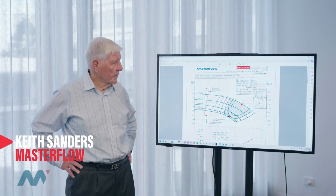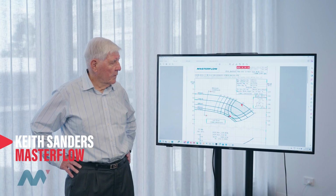On the screen we have a pump performance curve and there's a minimum continuous flow line. Can you elaborate on what this means? This is his recommendation for minimum flow in that pump, bearing in mind that the further you move to the left of best efficiency point, your impeller is going to start to come under various recirculation loads.